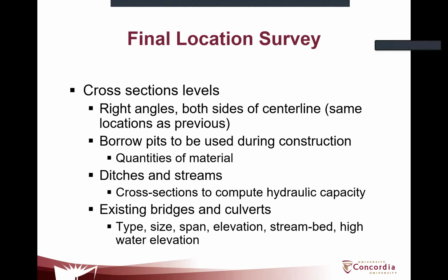You also need to look into the existing bridges and culverts and what you have right now, and whether the amount of water that your road will discharge into the bodies of water will impact the bridges and culverts, if the bridge is sufficiently high and if the culvert is sufficiently big in terms of the diameter, so that it can handle the future forecast once the road has been developed.